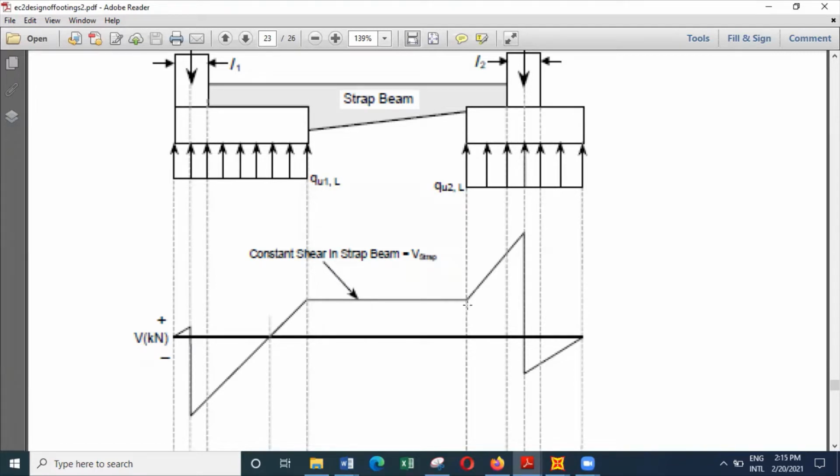to here. And then again, you can see some clockwise shear is acting. So this will start increasing again, go to a high value and then come back. Which means some of these shear forces will be acting on the footing, some on both the beam and the footing, and some of these shear forces can act only on the beam. So we have identified different situations. But when you consider the beam, the shear force is not a very high value on the beam.